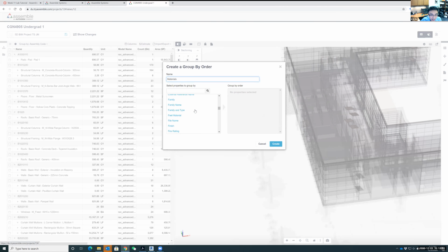All right, great. So now I regroup everything based on material. As you can see for this project, I do have concrete, doors. Let's say I'm the estimator of the doors. I want to see the location of the doors. I just do this. See, now with the X-ray view of this one, it's so intuitive. Let me go back to the materials.